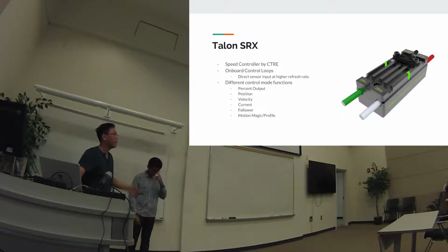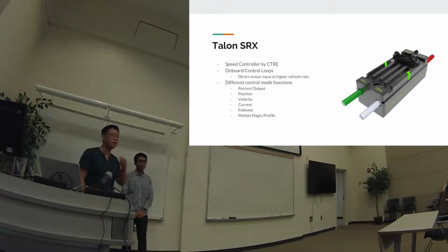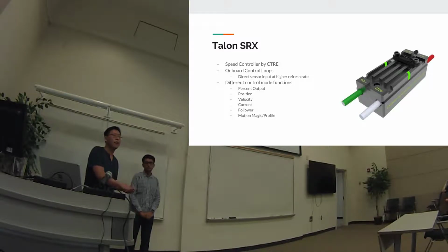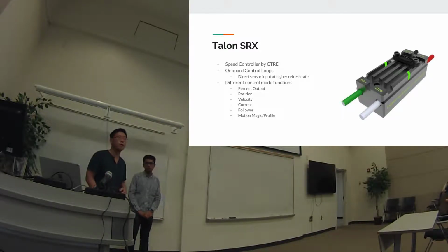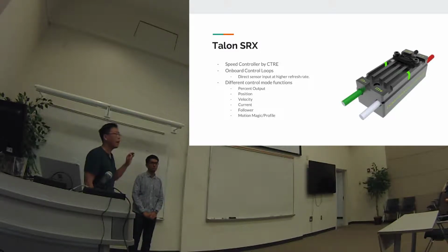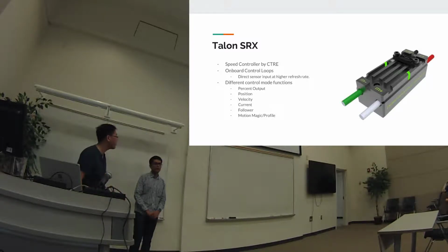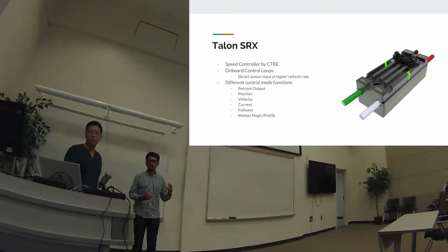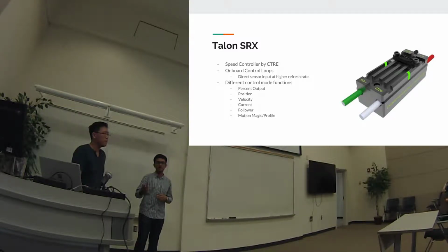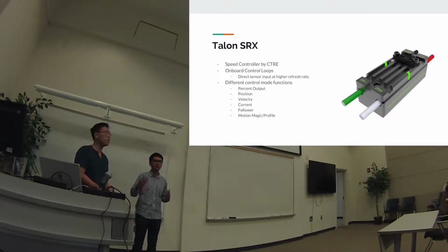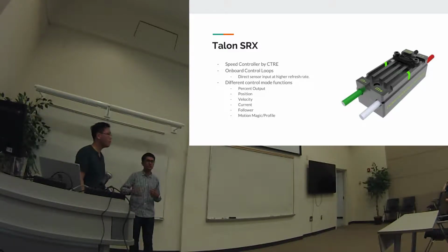And then also, if you guys aren't already using the Talon SRX, we highly recommend it just because it makes your life in terms of control systems so much easier, because all of it's kind of on board, and you don't have to necessarily write your own motion profiling code if you don't want to. It can also take in sensor data directly. Yeah, and the great part about this is it can run those sensors at really high refresh rates. So if you have an encoder, for example, and you wire that straight to the Talon SRX, in the code you can use the encoder as an input, and then send it to the control loop, like motion profiling or a set position, and it basically constantly uses that as feedback.